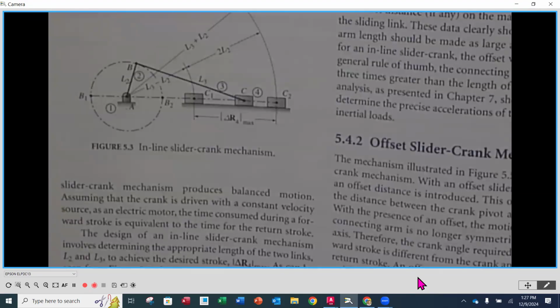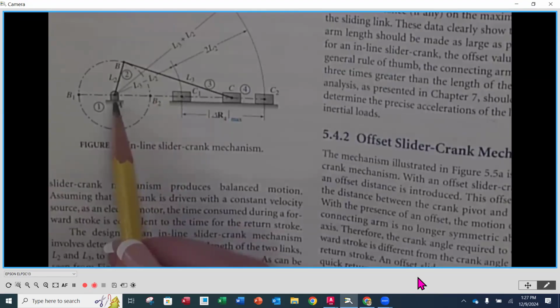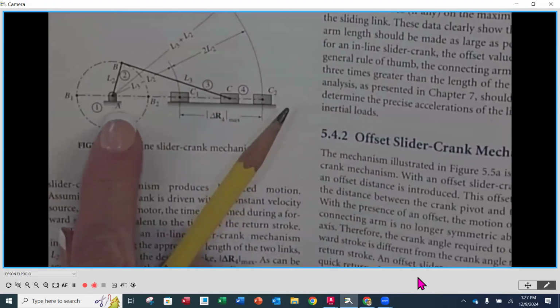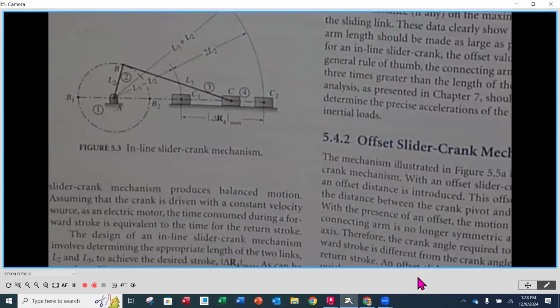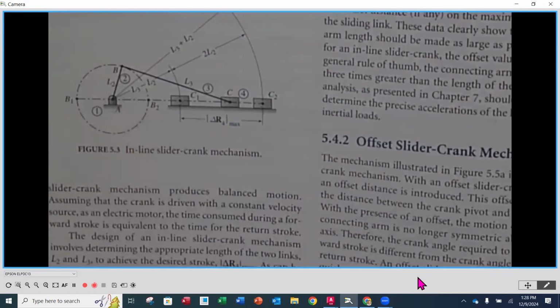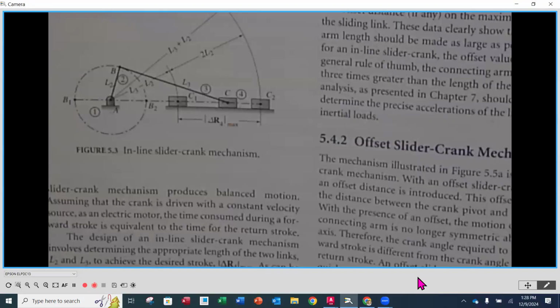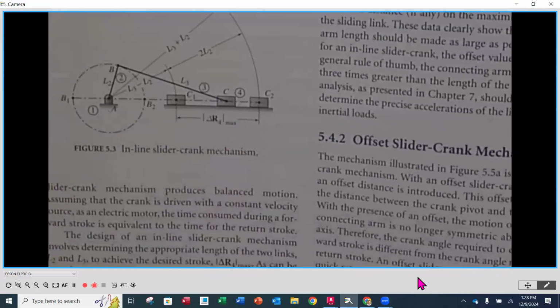As far as joints, these will be referenced in some of the equations coming up. Starting at the crank, A is the center of rotation for our first joint at the frame. B is the end point of our crank, just like we've been using since the beginning of kinematics. C is the center of our slider.